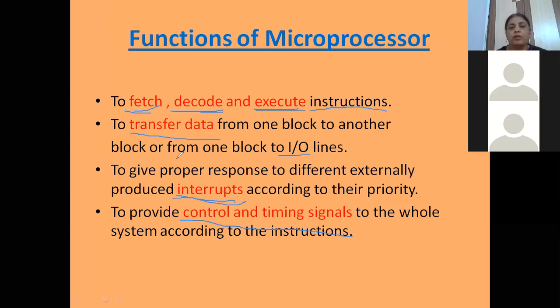So we have a big topic with interrupts of the 8085 microprocessor. We have two types of interrupts, hardware interrupts and software interrupts. When we are communicating with external devices, meaning input, output, memory, then it is called a hardware interrupt. And when the microprocessor is stopping itself, meaning you have given some program and there is an error in the program, the microprocessor needs to stop now. So it will stop by itself, and that is done by a software interrupt. So it is handled by the microprocessor.